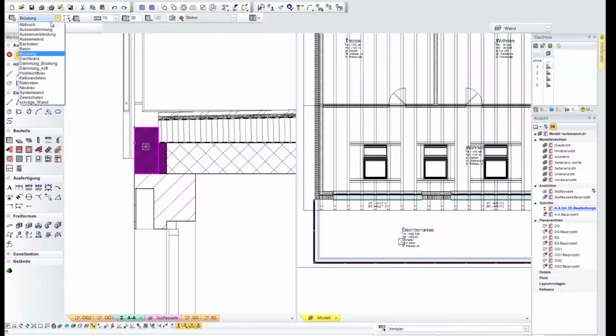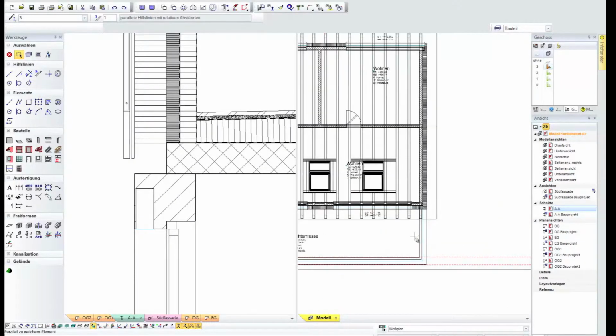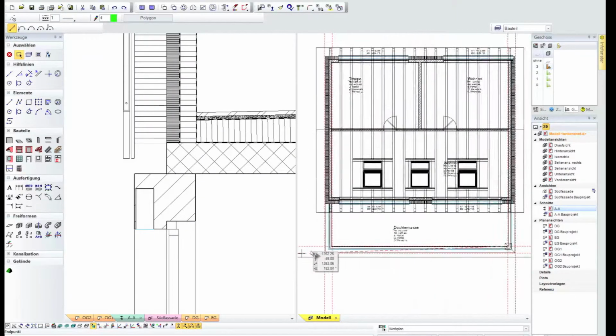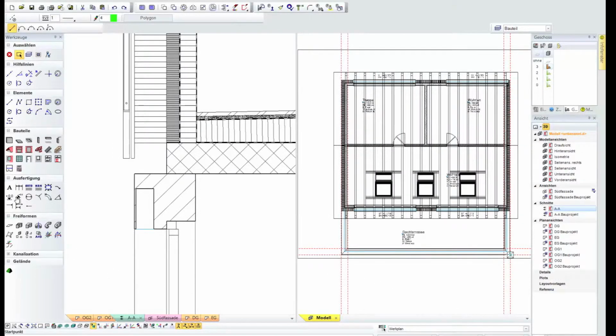To finish the edge of the roof, I now define the details of the roof edge. This consists of two parts: a vertical construction and a limiting layer at the top. I will now draw both these parts with a vector over this area. Once drawn, this vector defines the layers beneath it in a logically consistent way.